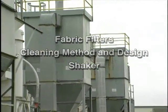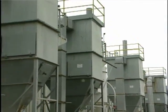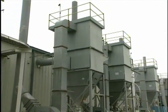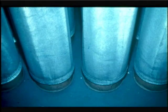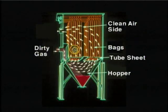As the name implies, shaker collectors clean the bags by gently shaking them. The shaker collector has a tube sheet between the vertical casing and the hopper. The open bottoms of cylindrical bags are attached to holes in the tube sheet, and the closed tops of the bags are attached to the shaking mechanism in the top of the casing. The contaminated gas stream enters the hopper, flows through the holes in the tube sheet, and into the inside of the vertical bags. Since the bags are closed at the top, the gas stream flows through the bags, leaving a dust cake on the inside.